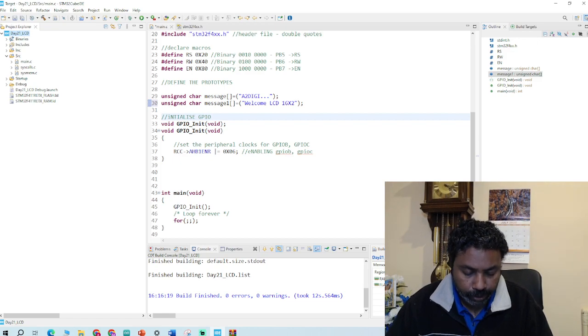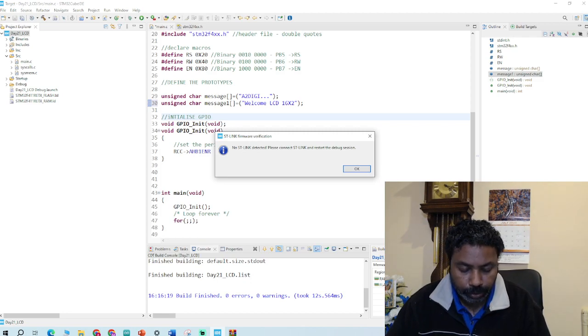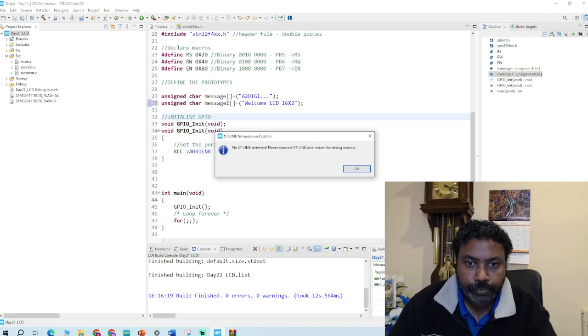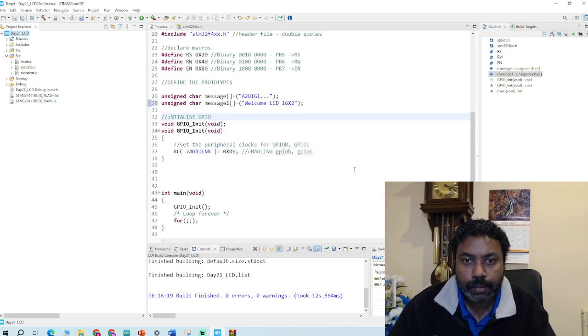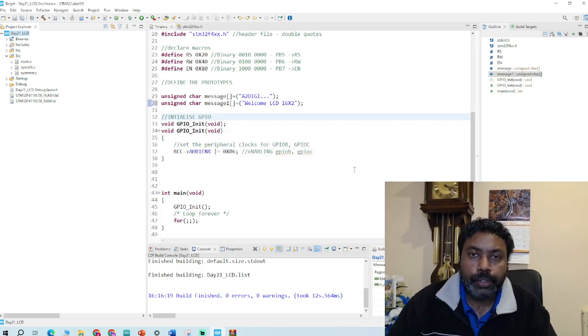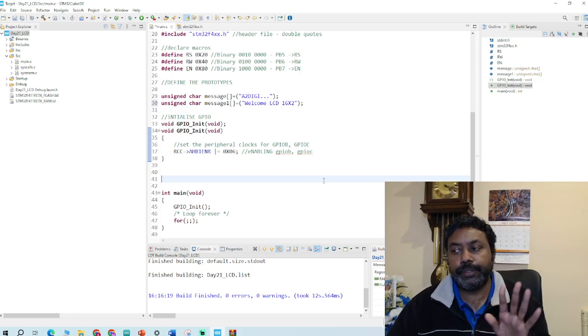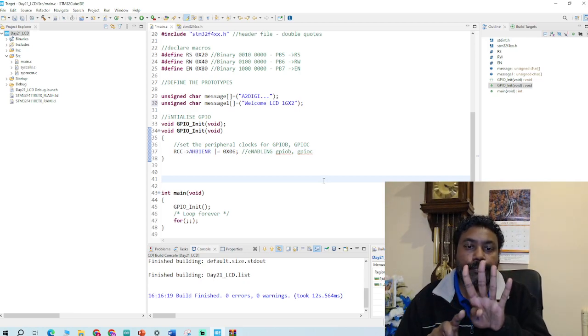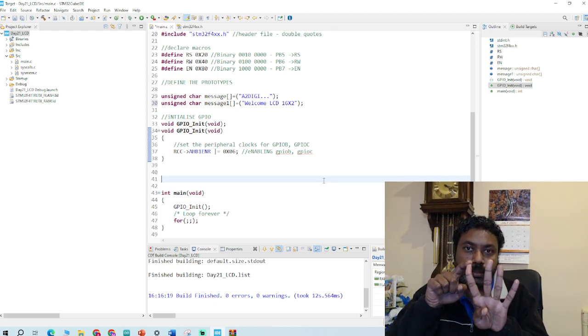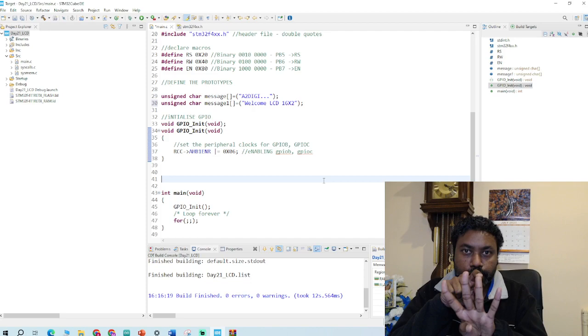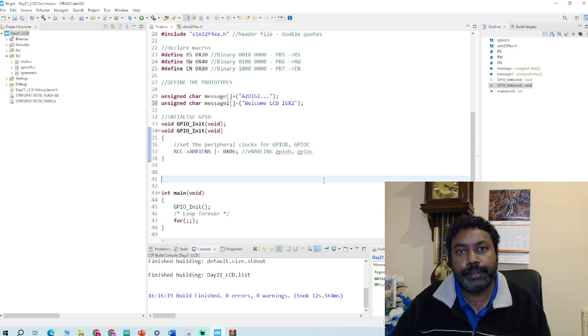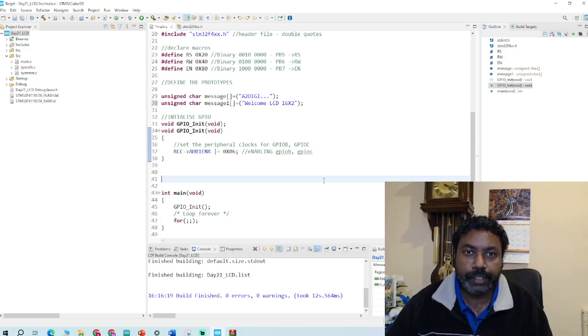Okay, I just want to show you the clock value 0x06 in the register. You will see that it's because you're enabling in a 4-bit field. Bit 0 is port A, which is 0, port B is 1, port C is 1, port D is 0, so 0110 is 6 in binary.